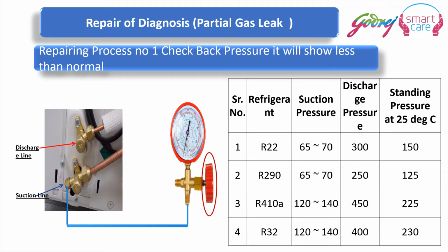The different suction pressures for different refrigerants in our Godrej air conditioners are given in this table. You can refer to this table for the suction pressures, and you can check for the respective refrigerant that the air conditioner is holding.